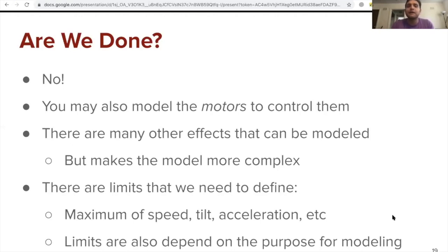And there are many other effects that I mentioned are not modeled, but, depending on the application, we should model. If we are flying in high wind, you probably need to consider the effect of the wind. You need to know that the drag effect depends on your speed, and what forces will be put on your drone, and all that goes into that F equals m times acceleration.